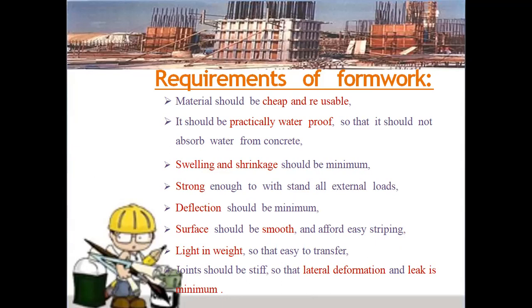It should be practically waterproof so that it does not absorb water from the concrete. If the material is not waterproof, water absorption from the concrete can occur in the formwork, and that is not good for the construction of the concrete cast.